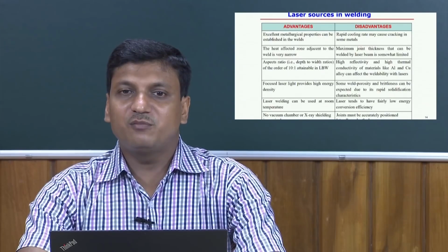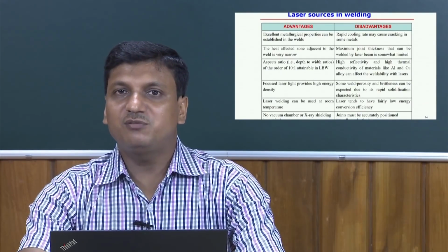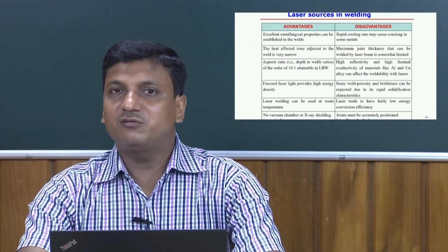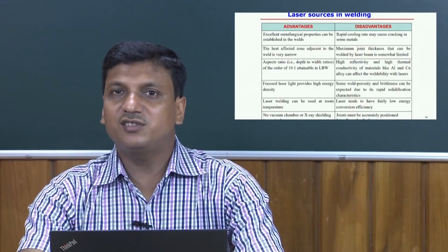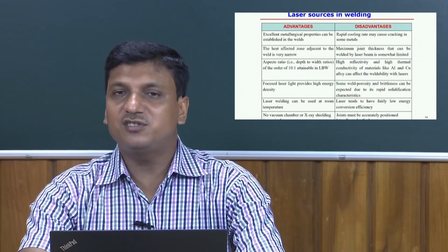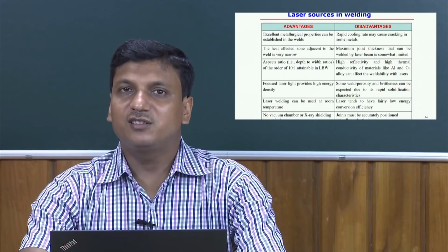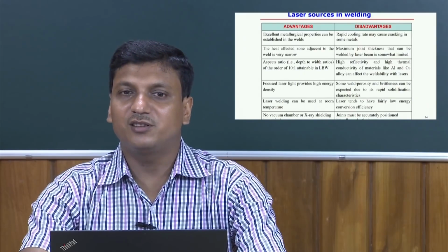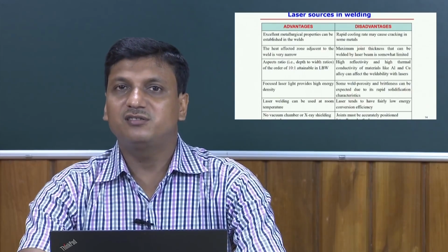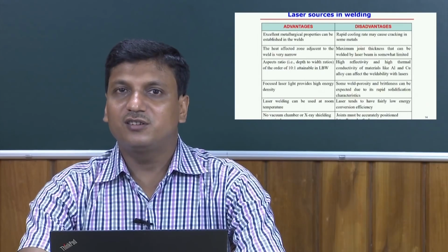Weld porosity and brittleness can also occur due to the rapid solidification, which is another disadvantage of the laser welding process. But the main disadvantage is that for the normal CO2 laser or Nd:YAG laser, the process energy efficiency or energy conversion efficiency is relatively very low, maybe around 30% or less. So, apart from the several advantages and disadvantages,